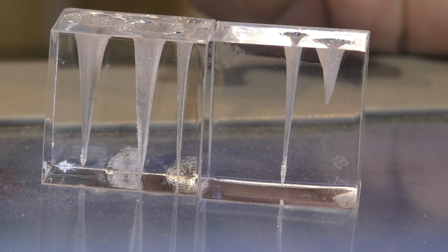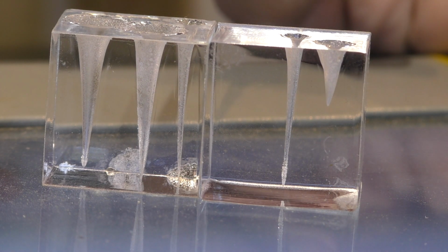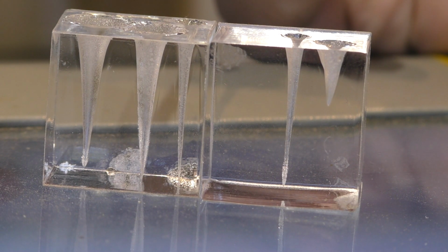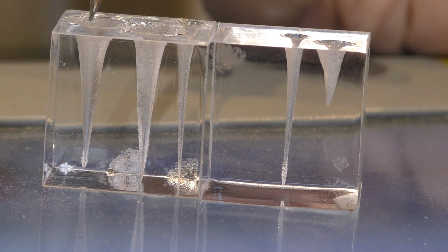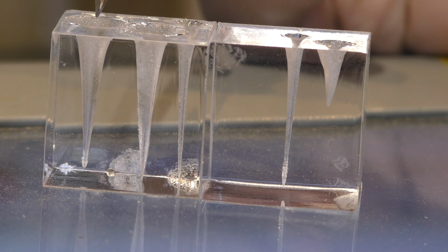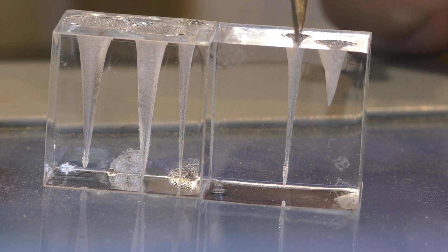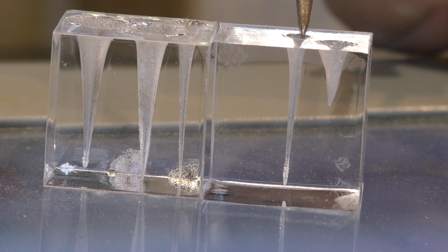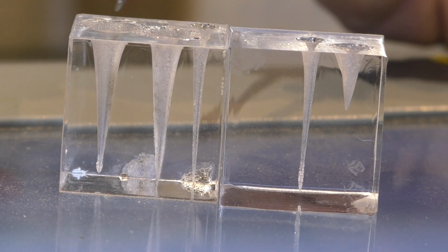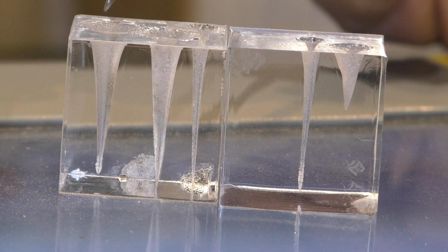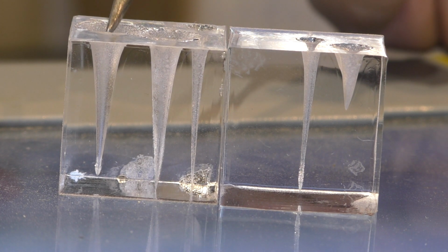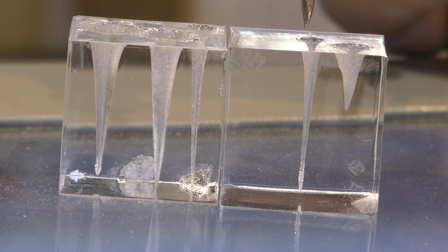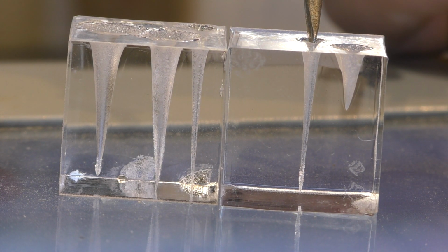Now, these are raw beams for comparison from the two machines. This one here is the raw beam after mirror 3, which is the beam that's going to hit the lens. And I've got exactly the same situation here from the RF machine. So the difference is that this beam is about 3mm diameter. This beam here is about 7 or 8mm diameter. Well, this is 8mm diameter with a 70-watt tube. And this is 3mm diameter with a 30-watt tube.